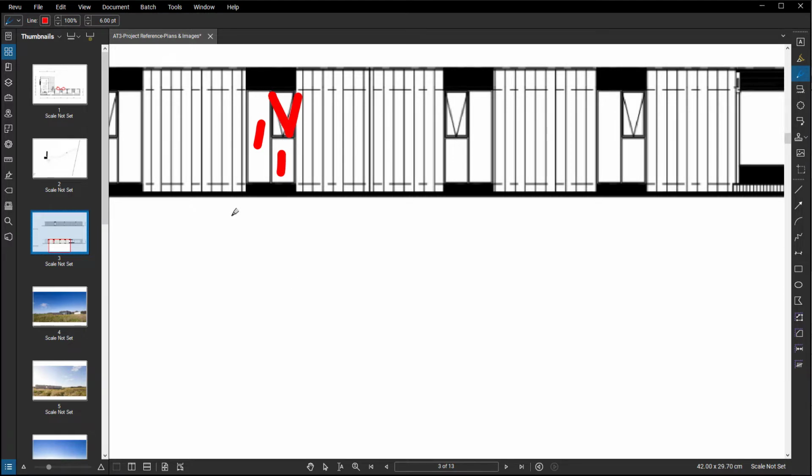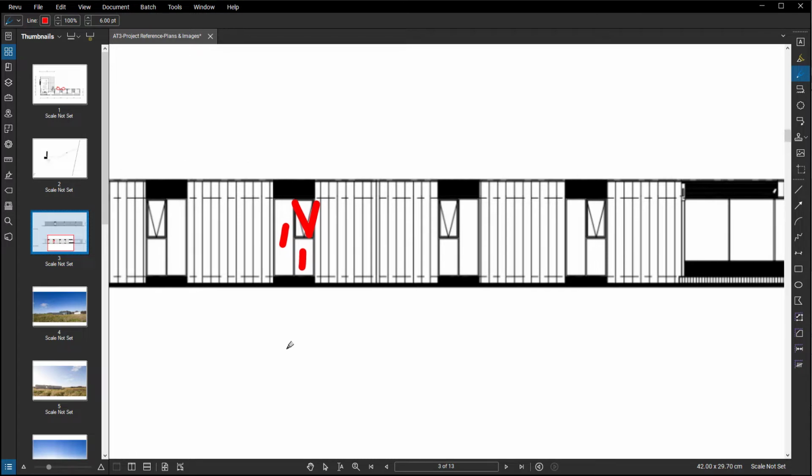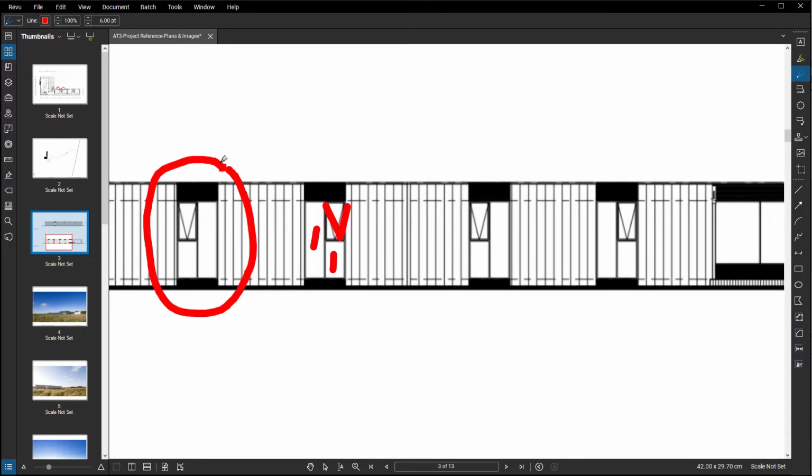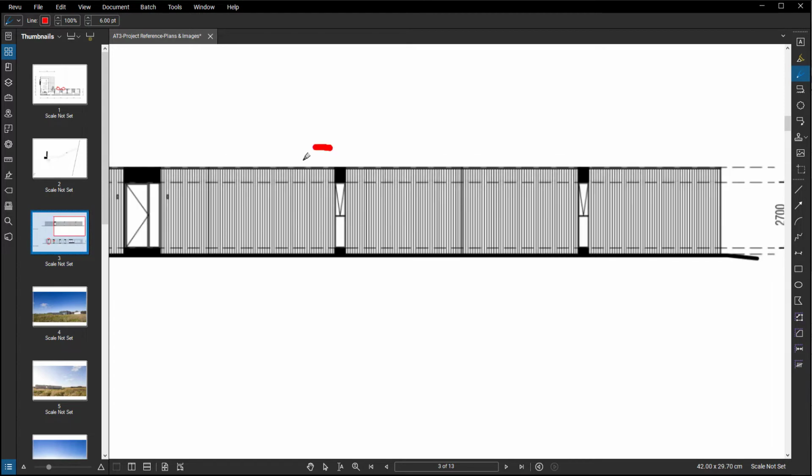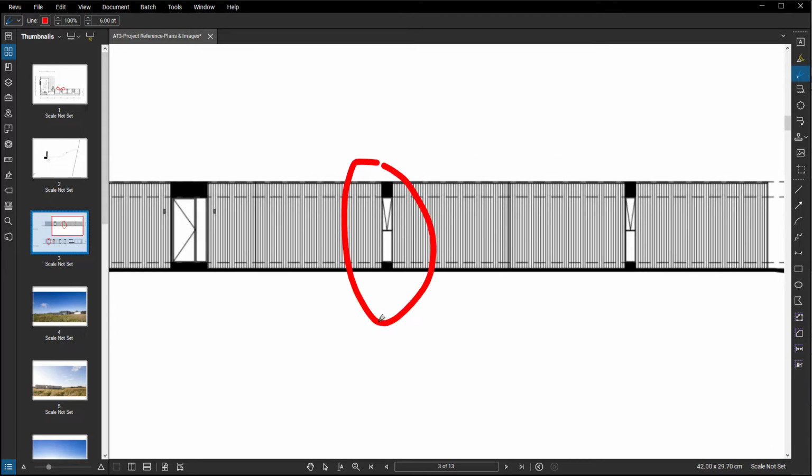You're free to design these windows however you best see fit. There's no right or wrong. I'm going to utilize the design that's already given to us and just use typical dimensions to reference in the creation of these blocks. The process is exactly the same for all other windows as well, whether they be just fixed glazed, sliding windows, or even the thinner awning windows on this side. Doors are different, and we'll go through them separately. They still utilize blocks, but the easiest way to create them is different to how we're doing this with windows.